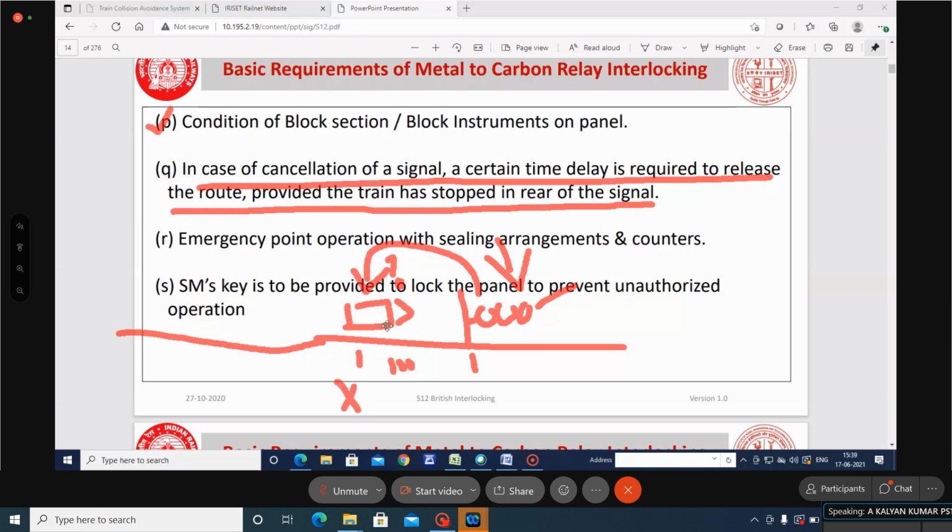He cannot control his loco to stand at the foot of the signal. So there is a possibility he will overshoot the signal. So what should be the minimum distance at which I can give the signal information so that he can comfortably control and stop his train?